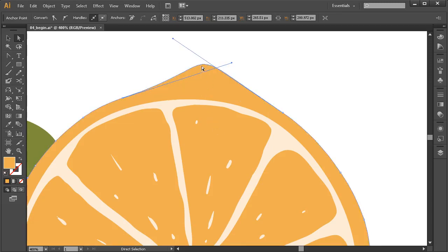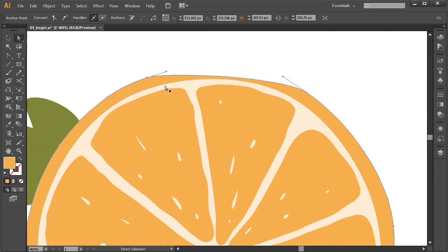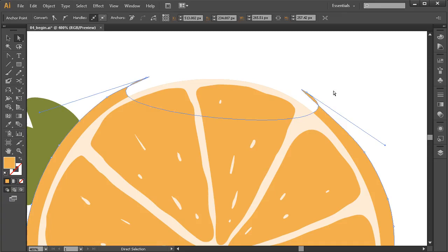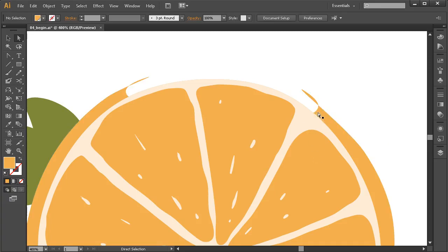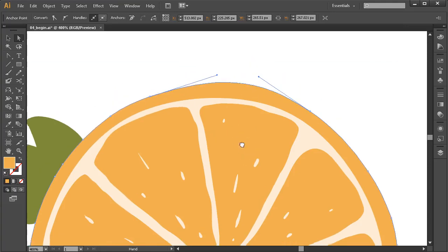Now, you want to be really careful in how you drag these path segments, because if you drag this too far, you're going to start to get strange overlaps in the path, which can create some really unexpected results. Let me click away, and you can see here that there's a loop that's formed in the path right here. And we've got a fill color, which we're going to learn about when we talk about attributes for vector objects. There's a fill color of this orange assigned to this object, and because this path makes this loop right here, we get what looks like a completely separate shape. So just something to be on the lookout for when you're modifying your vector shapes.